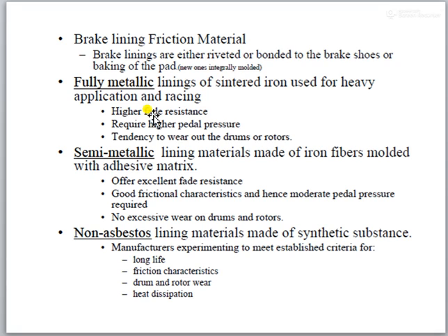The material's coefficient, the frictional coefficient, its value starts to decrease. So whenever the kinetic energy gets converted to heat energy, at that time due to the heat release rate, due to the increased heat of that substance, the coefficient of friction gets dull, or we can say that their frictional property gets dull. So such a thing is nothing but the fading.